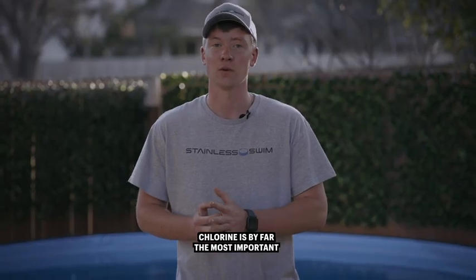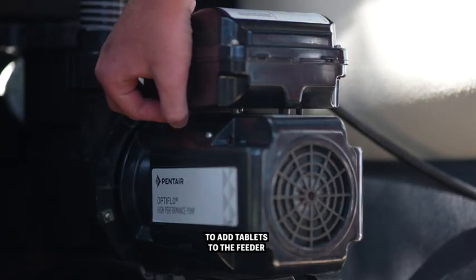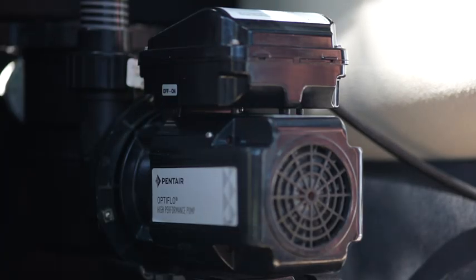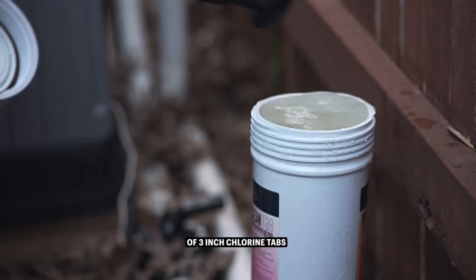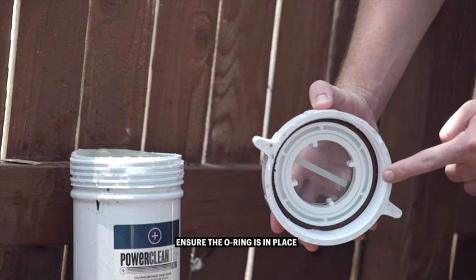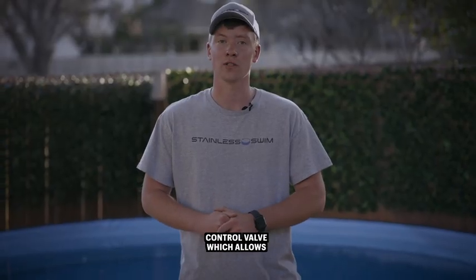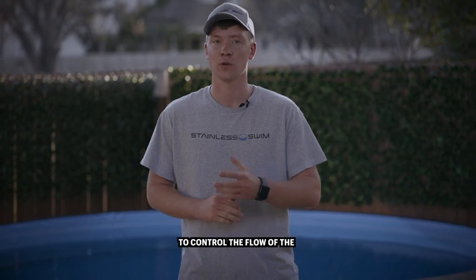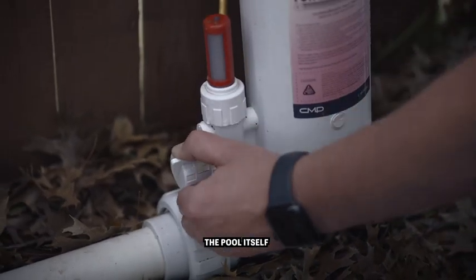Chlorine is by far the most important chemical to keep the water sanitized. To add tablets to the feeder, simply turn the pump off. Open the lid. Add the necessary amount of 3-inch chlorine tabs. Ensure the O-ring is in place and close the lid. The chlorinator also has a control valve, which allows you to control the flow of the water through it, helping you adjust the chlorine levels in the pool itself.